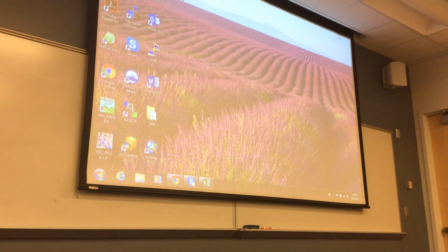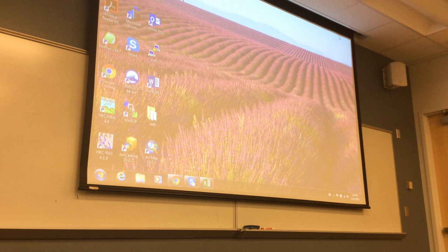Okay. So once we set up a model, we want to calibrate that model. What do I mean by calibrating the model? You want to compare your results to measured data to see if they make sense. Otherwise, how can you believe that you're representing this properly? Once we're kind of confident in our model, we're going to calculate our design for a given return period. Once we're done, we could have gone home here. If not, that land use in the watershed has changed. So we're going to change that land use and we're going to rerun the model to see what's the impact on our design. Does this make sense?